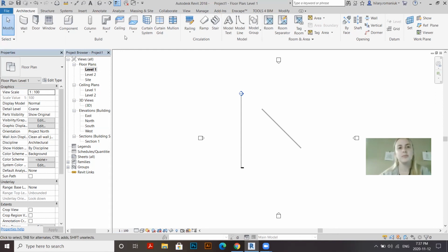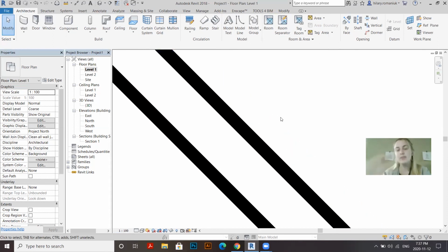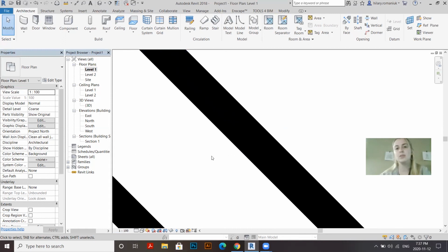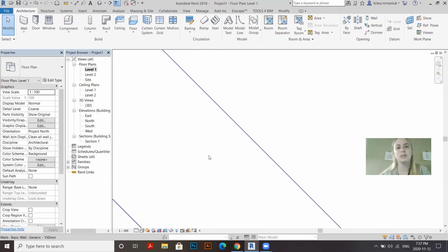That is right here. If I have it turned off, like I do now, when I zoom in, I can see that there's natural line weights that Revit assigns. And so when I'm working with something really detailed, it can be kind of challenging because those thick lines kind of obscure your view. So you always want to have thin lines turned on so that it's always paper thin.